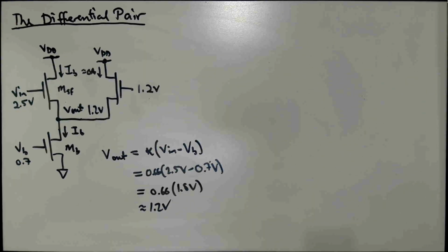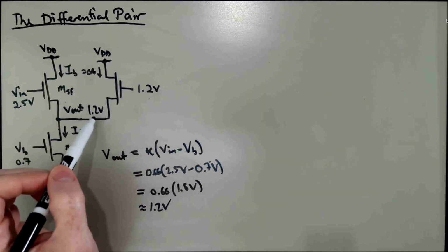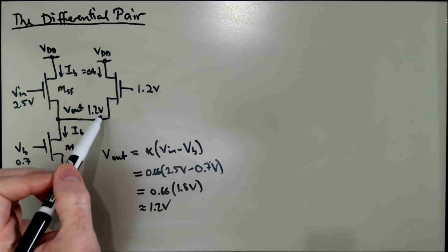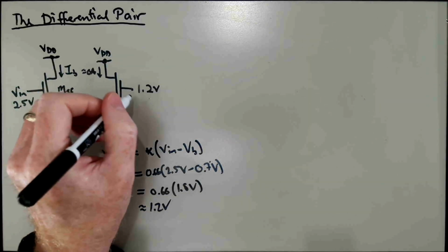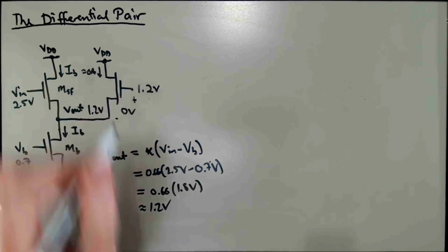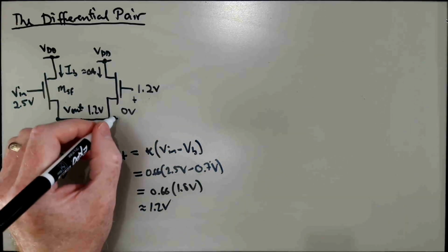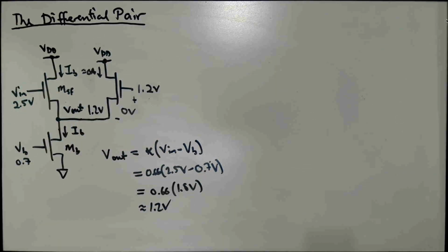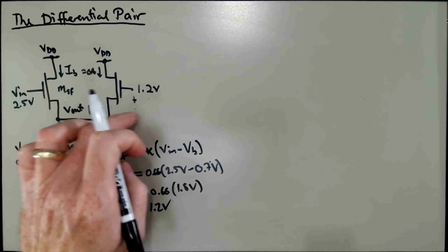Okay, what about 1.2 volts? Well, here, the gate to source voltage is 0. Right, so plus minus 0 volts. And at 0 volts VGS, we still have very little current flowing. So the question is, when are we going to start carrying current in this transistor?